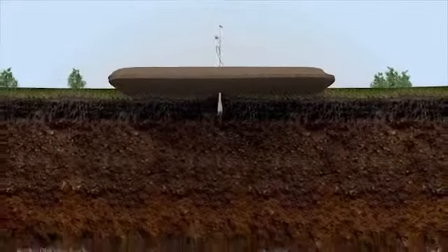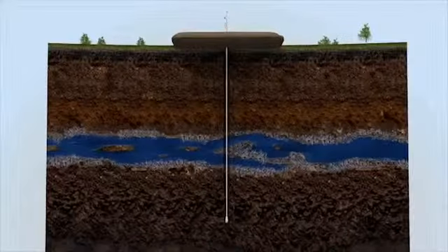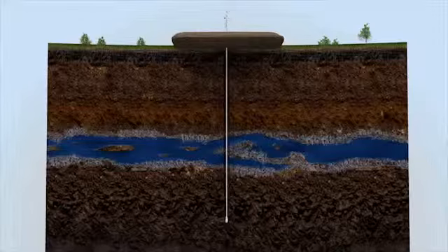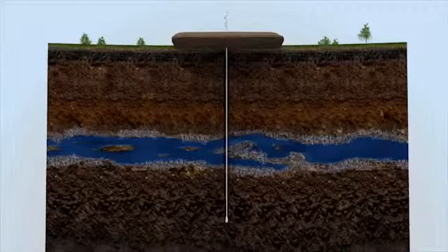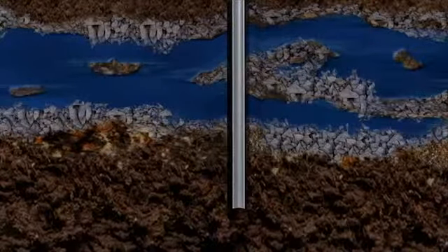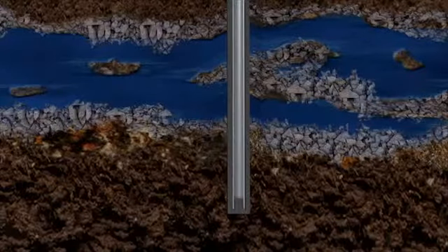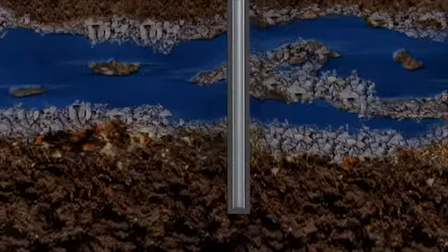The initial steps are the same as for any conventional well. A hole is drilled straight down using freshwater-based fluids, which cools the drill bit, carries the rock cuttings back to the surface, and stabilizes the wall of the well bore. Once the hole extends below the deepest freshwater aquifer, the drill pipe is removed and replaced with steel pipe, called surface casing. Next, cement is pumped down the casing. When it reaches the bottom, it is pumped back up between the casing and the borehole wall, creating an impermeable additional protective barrier between the well bore and any freshwater sources.